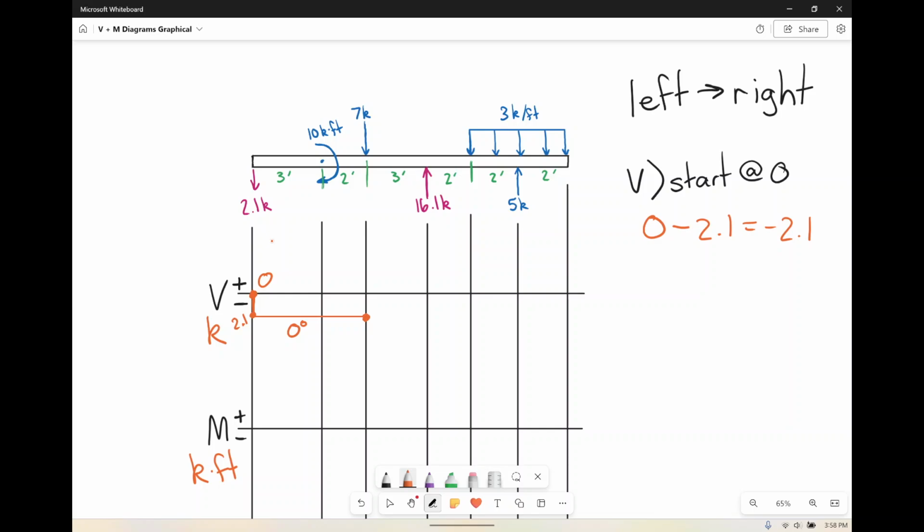Literally, if you just take a cut, right? We go back to equilibrium of a deformable body. If you take a cut here versus taking a cut here, and you find the shear force, you're going to discover it didn't change. Hence, what we're actually doing on this diagram is just denoting that anywhere in those first 5 feet is not going to change.